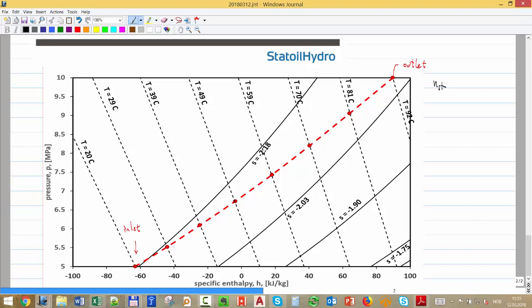Okay, and that's the suction to the first stage, the discharge of the first stage. Then that will be the suction of the second stage and the discharge of the second. And we assume, that's an assumption to model this process, that the polytropic efficiency of the stage, or the polytropic exponent of the stage, both are equivalent, is equal to the polytropic efficiency of the whole compressor,